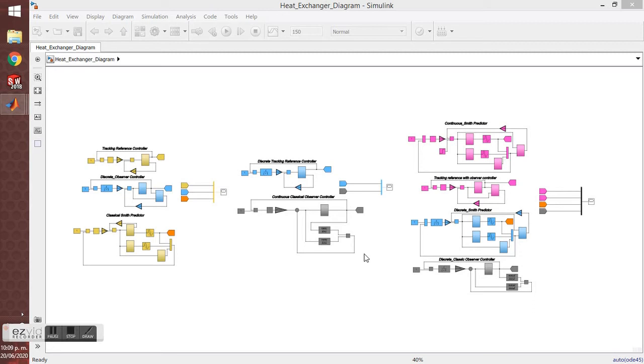Most of the industrial processes present delays in their dynamics. A typical example in the industry is a heat exchanger. Delay is a phenomenon that occurs due to a temporal displacement that can appear between two or more control variables, and this can be generated, for example, by the time necessary to transport mass, energy, or information. The following figure shows the control, both in the continuous and discrete domain, of some controllers that allow the tracking of the reference by means of the implementation of observers.